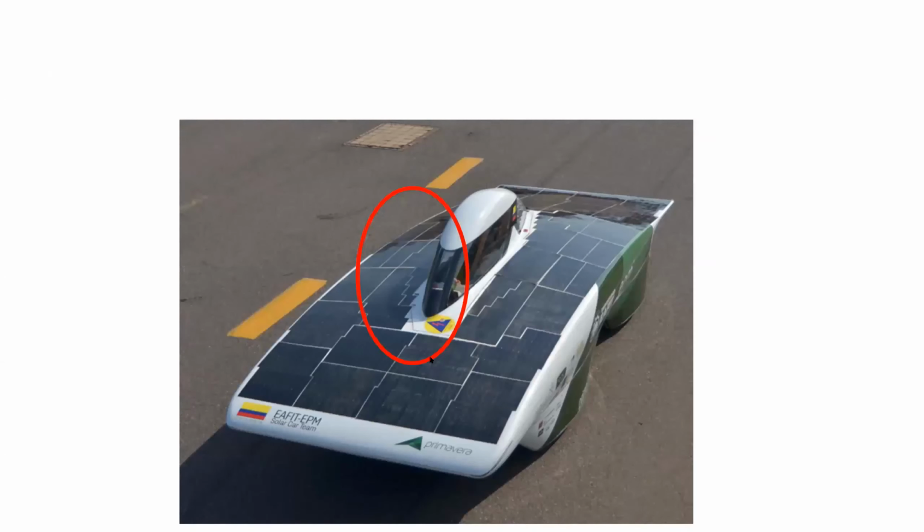Examples. So one thing that commonly happens with solar cars is that you want to make an aerodynamic solar car, which basically means that you usually have a canopy on the solar car, and when the sun is low enough, that generates a shadow on your solar array. Another thing that you can see here is that because of the aerodynamics, the car has a certain shape, which is not flat, and that causes every solar cell to be at a different angle with respect to another solar cell. And then because of that, there's a different amount of irradiation on every single solar cell, which causes some problems when you put them together in groups.